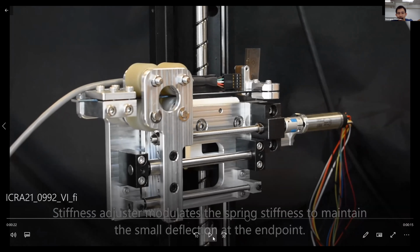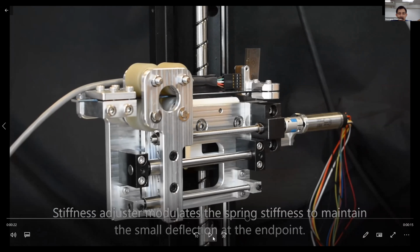If the support stays far from the endpoint, a human who touches the robot at the endpoint can feel that the robot is very soft. We can use a small magnitude of force to make the spring deform. But when the robot senses that the deformation is too high, it will change the position of the roller support to be closer to the endpoint to increase the stiffness at the endpoint.